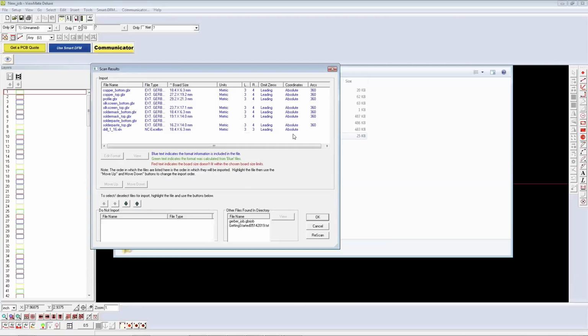Double click it. You notice that it'll pull away anything that is not a Gerber. The other thing you'll notice is that these files have formats, okay? Right now, these are the default formats that ship with Eagle. They're metric 3.4 and the drill files 3.3. All of this format information here is not carried in the Gerber itself, okay? The Gerber Viewer makes an educated guess at the formatting. It's not always right, okay?